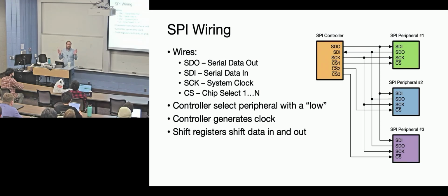I would just point out that in a few years, you will be in the position to name the naming conventions for your bus structures. Whenever you make a peripheral, you get to name it. That puts the responsibility, or at least the opportunity, back in your hands to choose bus structures that will be more inclusive. But since there is no spec for SPI, you'll still find documentation that names it both ways. So it's up to you to understand. In this class, we'll just use SDO, serial data out, and SDI, serial data in, and most companies have switched their naming conventions.